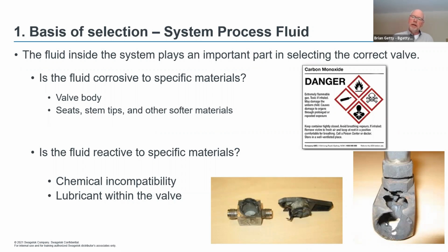The next photo, as you can see here, is another one of our applications where the customer had picked the right valve. He picked a severe service needle valve. So they picked the right valve for, again, another system of high concentration oxygen. So they picked a needle valve, which was great. The only thing that they forgot to do is ask for it specifically cleaned. With Swagelok, it's called an SC11 cleaning. We don't specify products cleaned for oxygen, we just specify the cleaning system, and if you look at the specification for cleaning for oxygen and our specification, they're identical. It's the same thing.